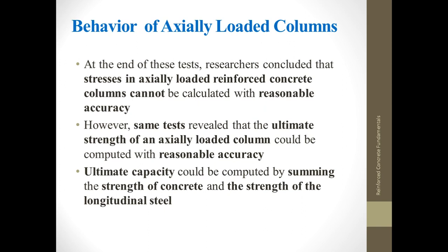But one thing they learned from their tests was that the ultimate strength of an axially loaded column could be computed with reasonable accuracy. Researchers found that the ultimate capacity could be computed by summing the strength of concrete and the strength of the longitudinal steel.